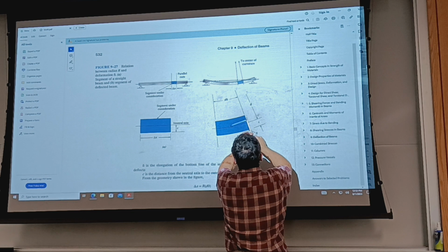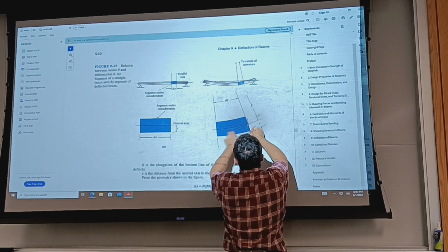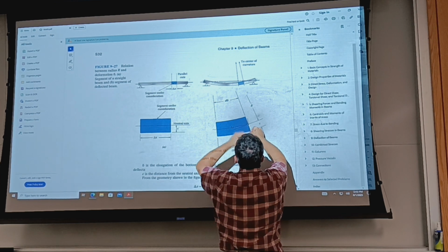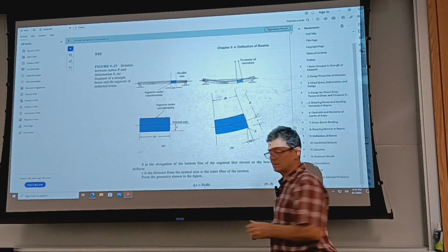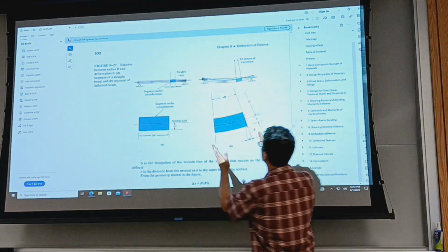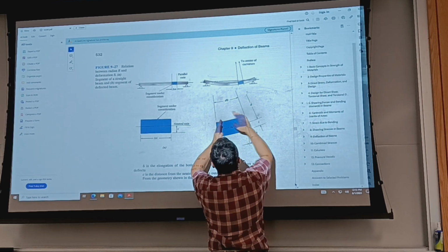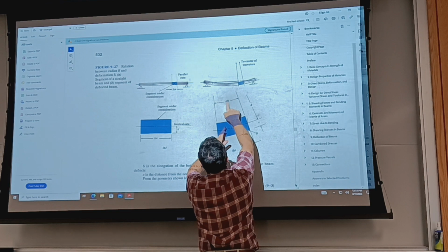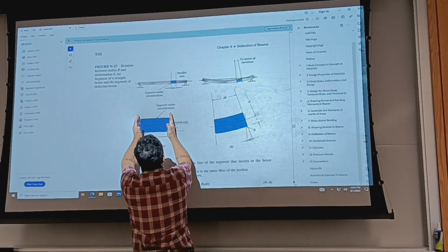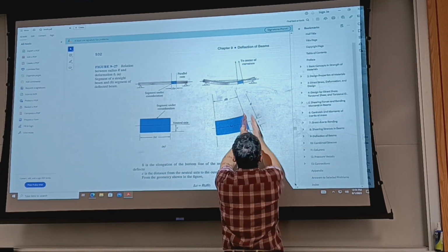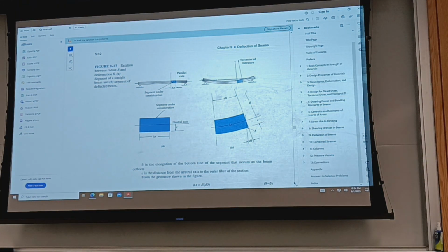Likewise at the other end of the short piece of the originally long beam, it's also 90 degrees. Because the end sections rotate, I have this angle d theta. It's also the angle measured if I take this plane, translate it, and measure relative to the rotated end. That's also d theta.